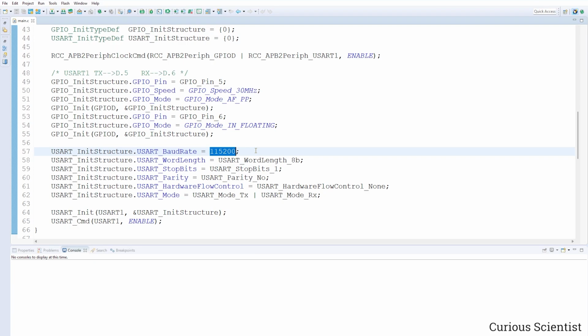And if the two baud rates differ, on the receiving and sending side, then on the receiving side, which is what you see, you will receive garbage characters because of the different baud rates. So make sure that you have the same exact baud rate on both sides.